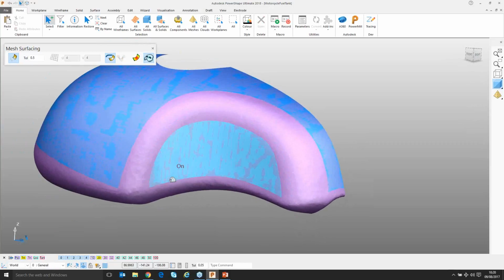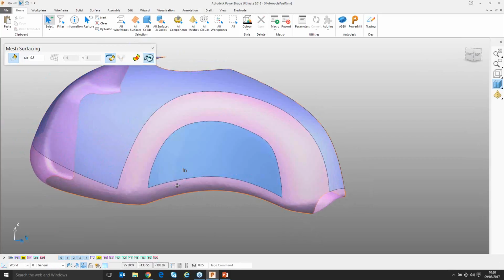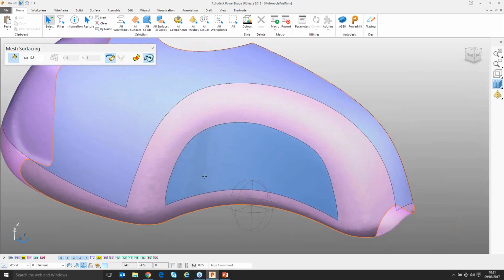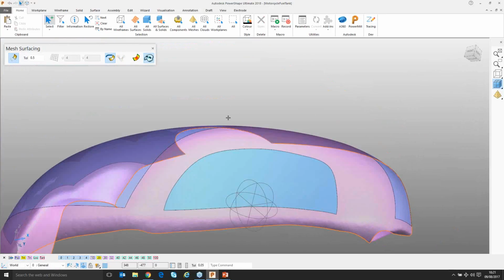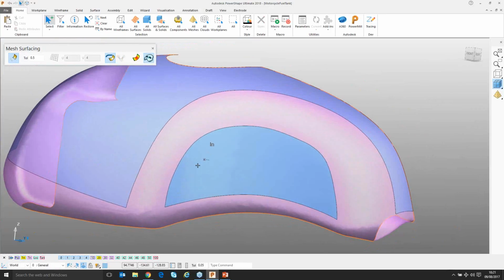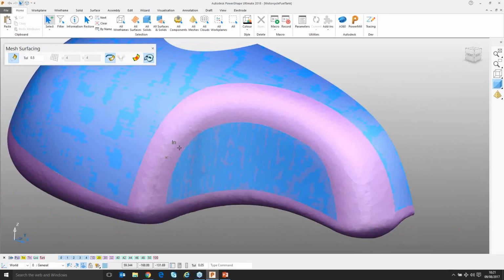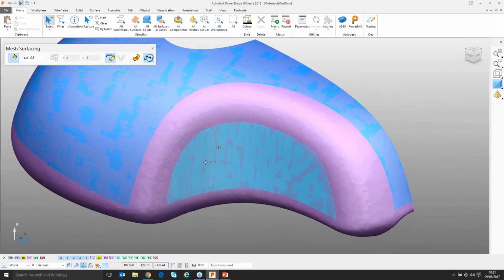I quite like to use the F4 key when doing this kind of work because F4 changes the shading view to be shaded but semi-translucent, so I can really see clearly the edges of the surface while still seeing the triangle set. So that was the F4 key. To toggle back, of course, just go back and hit F4, or F3 will give you the original solid view.